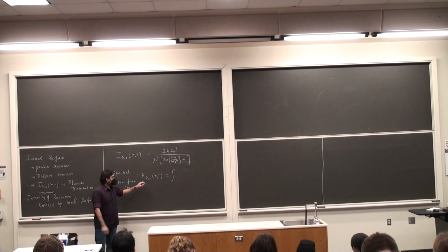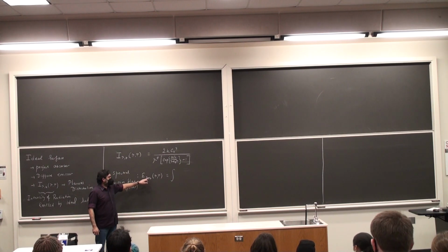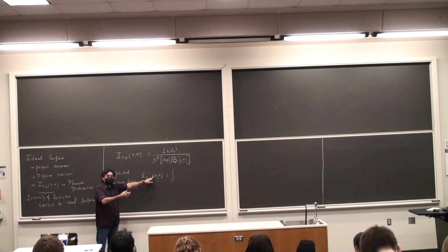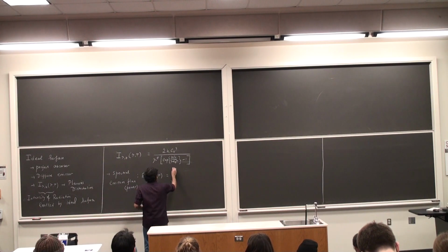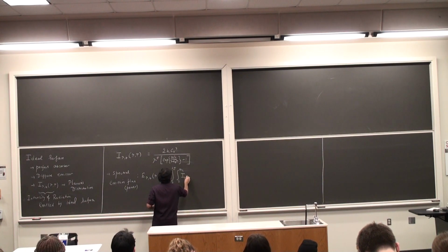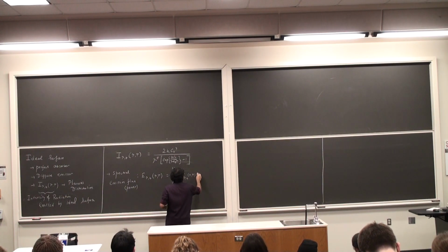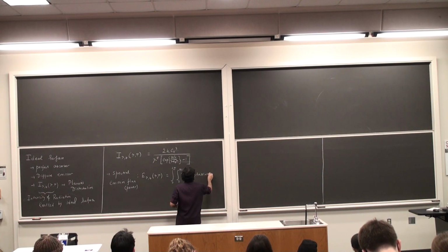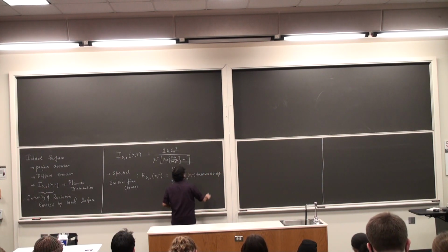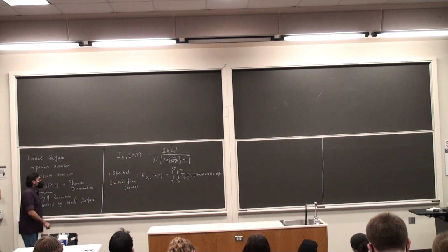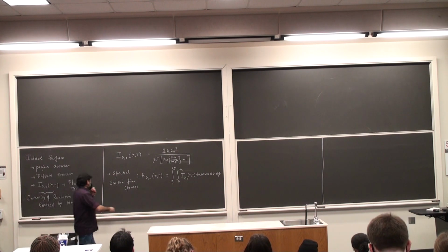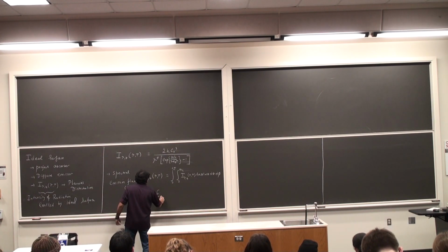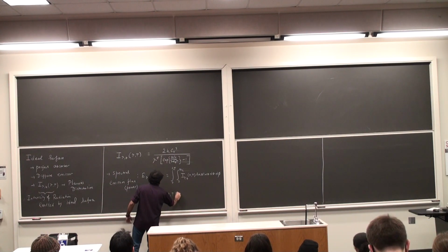So this is an integral, and notice if you have a subscript given and you see that the functional dependence does not have anything based on the direction, it means the integration is done over all the directions. So this is going to be 0 to 2 pi, 0 to pi by 2, I lambda,b, sine theta, cos theta, d theta d phi. But I lambda,b is independent of theta and phi, so I can remove it out of the integral, and I eventually end up getting E lambda,b is pi times I lambda,b.